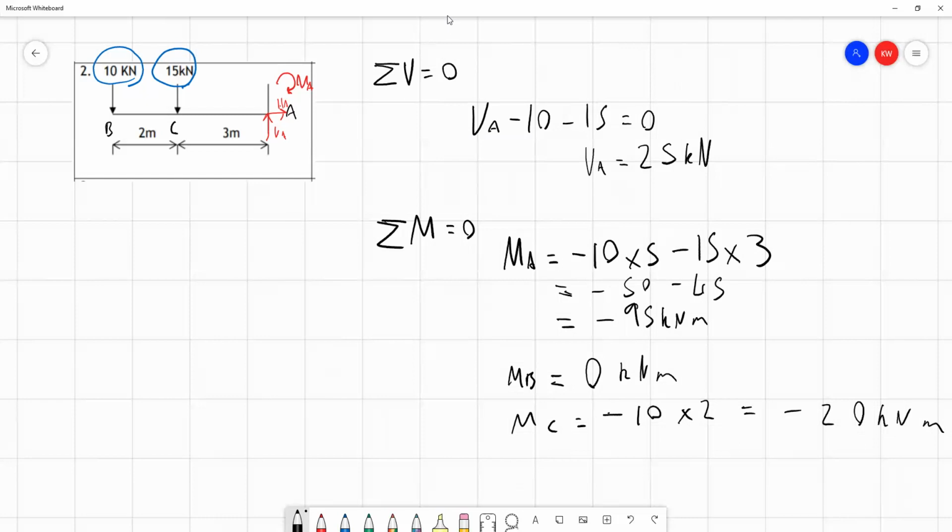So let's have a look at a shear force diagram now. I won't bother with the ruler, I'll just do this a bit roughly. I'll draw a line here for our diagram to begin. So this is our baseline of zero shear force. I'll mark these zeros here. Now what's happening as we move across our beam? Well, if we start on the left-hand side at point B, immediately we have a downwards shear force of value 10. I'll draw it down here. So this is taking us to minus 10 on our shear force diagram.